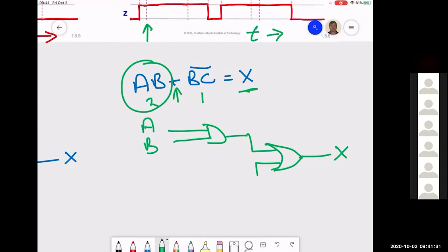The other one has a NOT symbol, an inversion. So I've got rid of that NOT. I've got a B and a C. It's an AND. The B can tie up to the other B, and we have our answer. Okay. So once again, it's a systematic system of small steps. Break it down into small steps and just solve it in a sequential, logical manner.